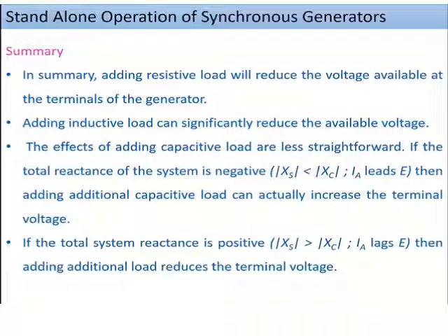Summary. So if I am adding a resistive load, it is a case of a unity power factor, the voltage reduces at the terminal. If I am adding an inductive load like an induction motor, then the voltage reduces significantly. The effect of capacitive load, that is leading power factor, is less straightforward.